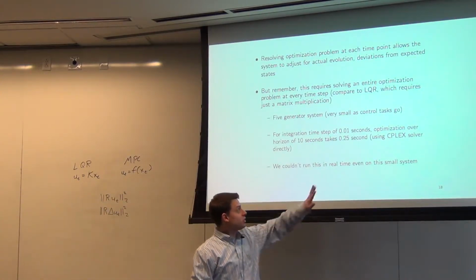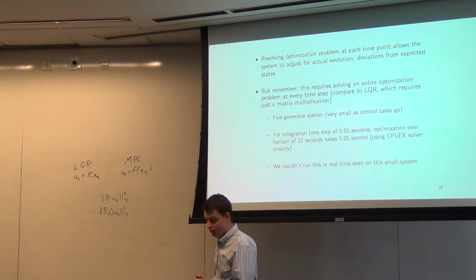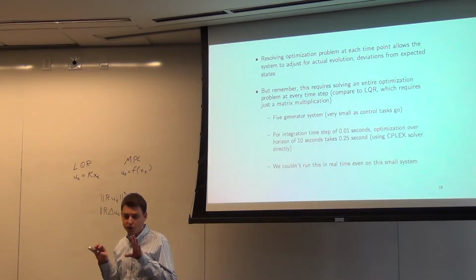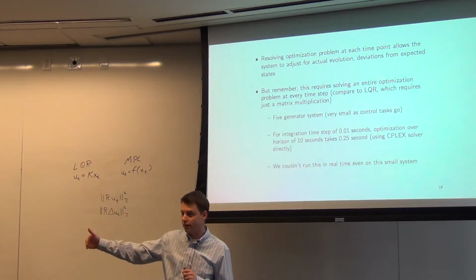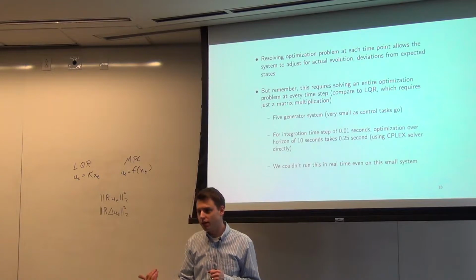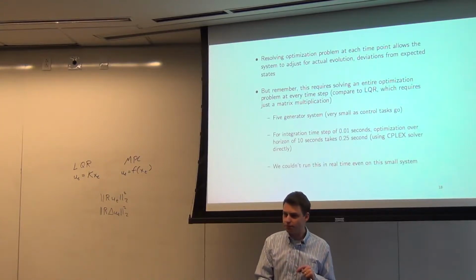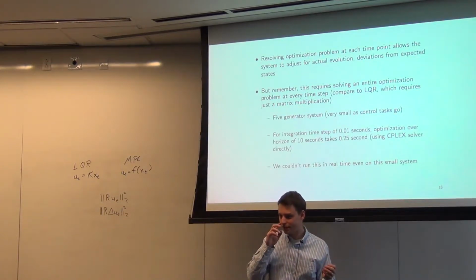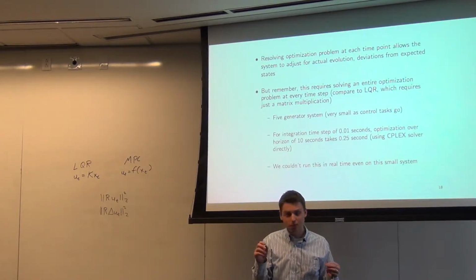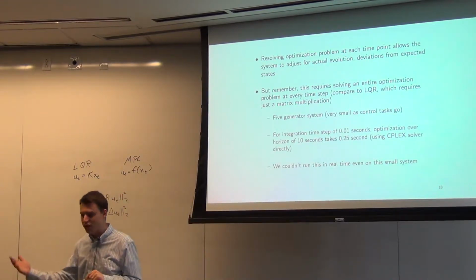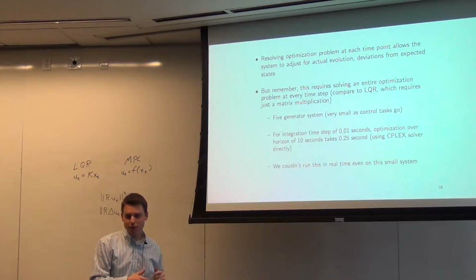So it could be that for some problems, and I'll really admit this, MPC really isn't that well suited. The number of tasks where it can be applied, though, is increasing a lot, just because computational power is speeding up. A decade ago, MPC was sort of unthinkable for any kind of real-time control task. Now it's used there all the time. Maybe 2 decades ago, it was unthinkable for that. Now it's used there all the time. Okay, so there is some sort of natural progression of computing which will make this more applicable.